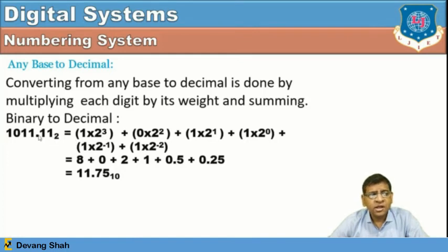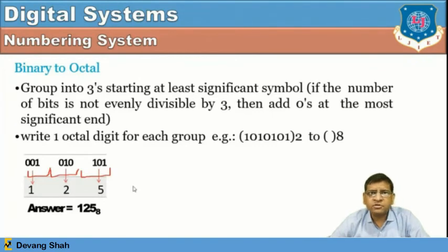So you can see there, this one is nothing but the position of 2 raised to 0. It starts from the LSB, the least significant bit. Then the decimal equivalent number is 5. 010, the decimal equivalent number is 2, and 001, the decimal equivalent number is 1. From that particular table, we find that 5 is represented in 3 bits as 101. So if you have a binary number and you take groups of 3 bits from LSB to MSB, you can easily convert any binary number into an octal number.